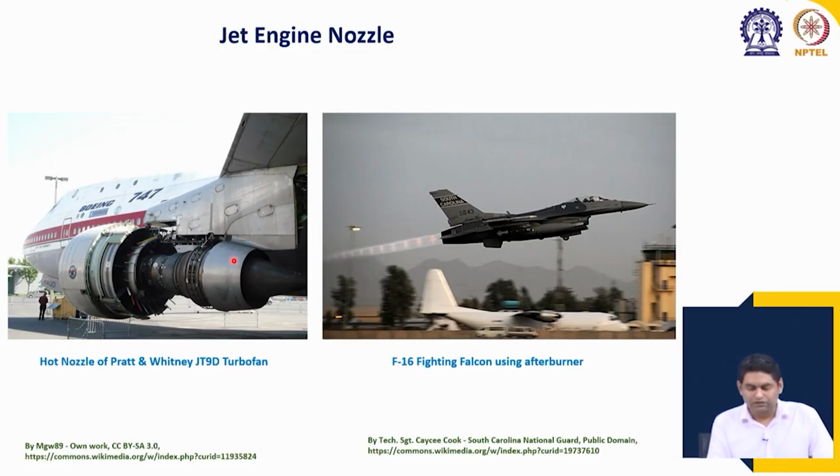Okay. So, you can see how the nozzle acts, again the same diagram showing that the nozzle is accelerating the fluid, the nozzle cross section area is decreasing nicely and it is accelerating the fluid, creating the thrust. Here you can see the inner nozzle of a two nozzle engine; these are known as turbofans. So, there is one inner nozzle, the hot nozzle, and one outer nozzle which is not shown here directly, the cold nozzle. This is from the Pratt and Whitney high bypass turbofan engine.